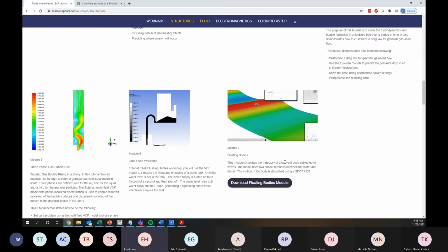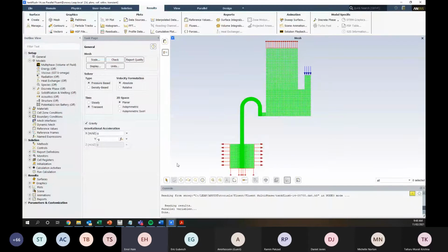Can you show us how to set Fluent to always save the case data under .h5 format? A .cas format won't retain overset mesh connectivity. That's true. It also, I think, doesn't save as much information about DPM. It also is faster to read and write.